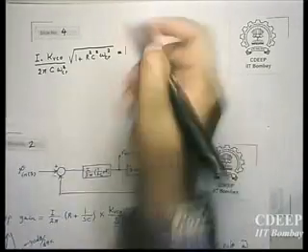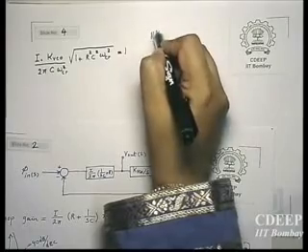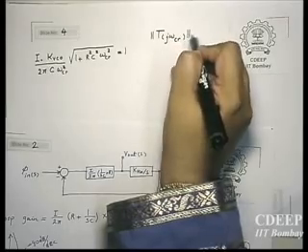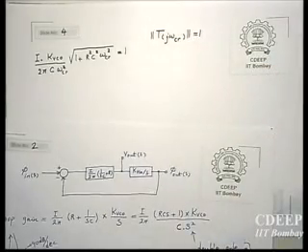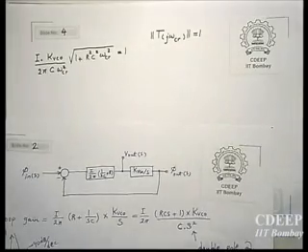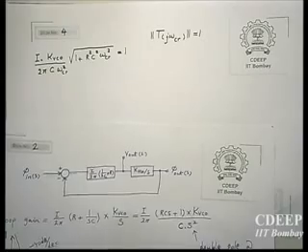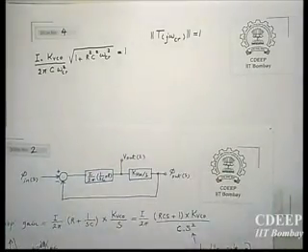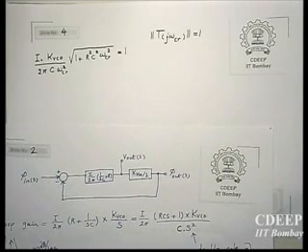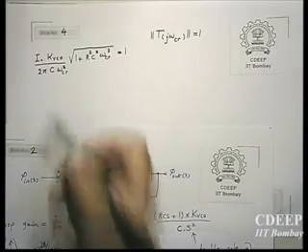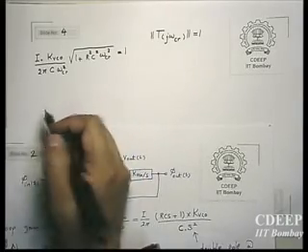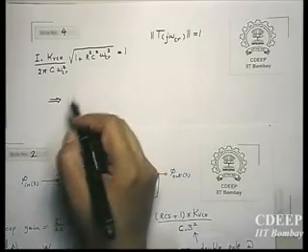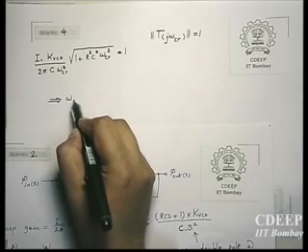So what I did is make the magnitude of the loop gain at crossover frequency equal to 1. We want to see what the crossover frequency will be, which is eventually close to the bandwidth of the loop. This is the open loop gain. The crossover frequency of the open loop gain will be almost, not exactly, the closed loop bandwidth of the loop. So you make it equal to 1, and therefore from here it will be this.